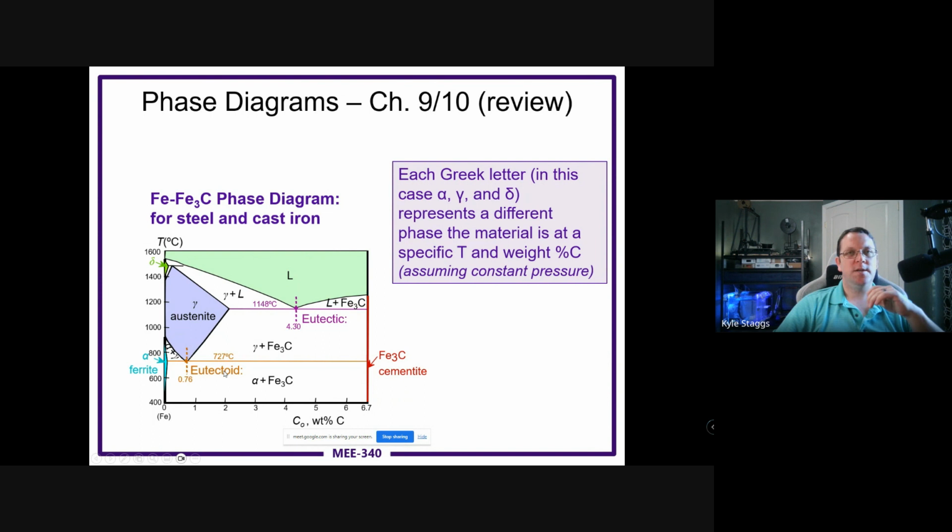So that's the easiest way to remember those, is thinking of those as being the bottom of the valley for a phase transition. So anytime you're confronted with questions about that, because all these different phase envelopes are describing some regions, and we add in these lines to help understand what happens. And so these gamma crystals tend to reform into various ferrite or alpha crystals plus carbide below this 727C. So each material is going to have something like this.